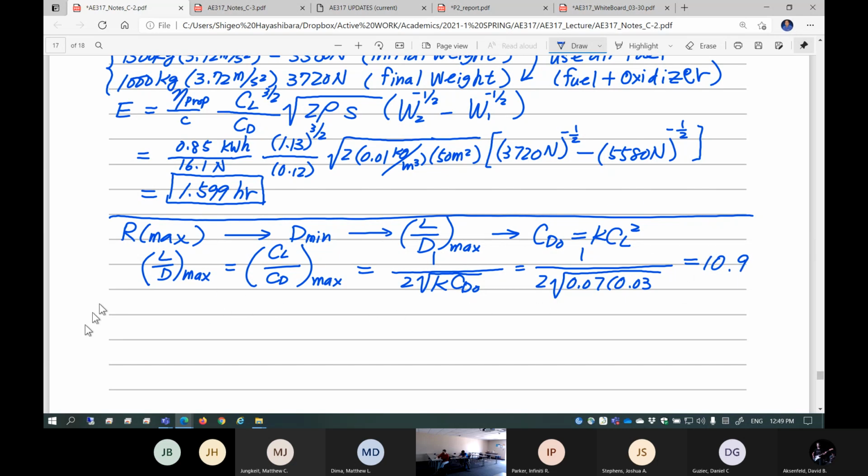Obviously, as you design your airplane, X55 actually gives you this value. It actually plots lift to drag ratio over the range of alpha, right? So for maximum range, you are going to plug in once again to the Breguet range equation, which is eta prop, propeller efficiency, divided by BSFC, times CL over CD to the max, times natural log of the ratio of initial weight W1 to final weight W2.